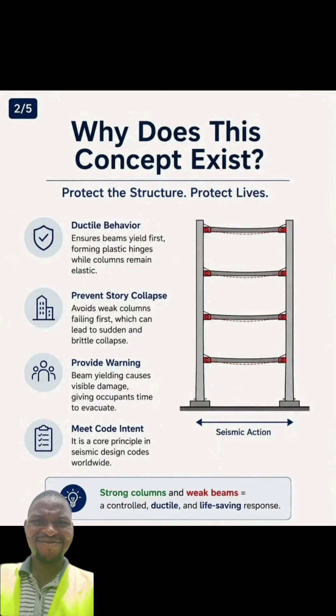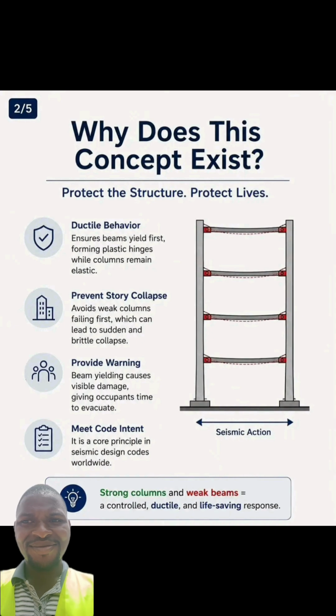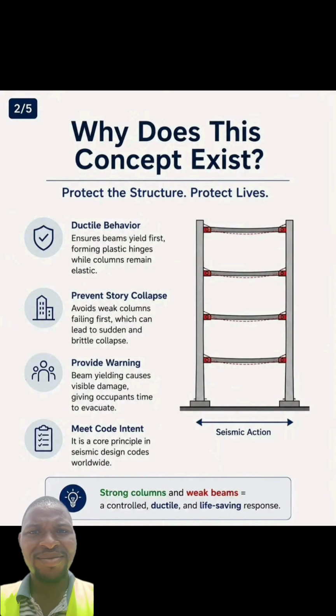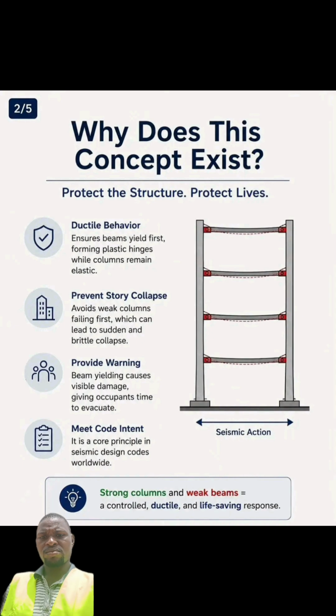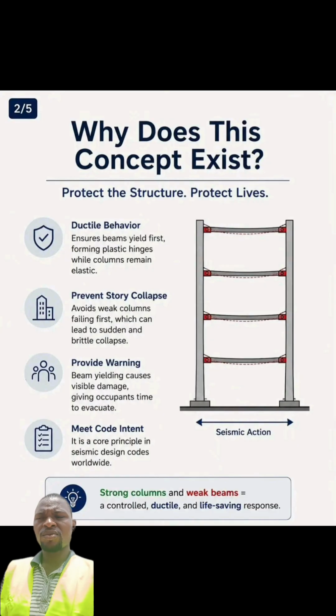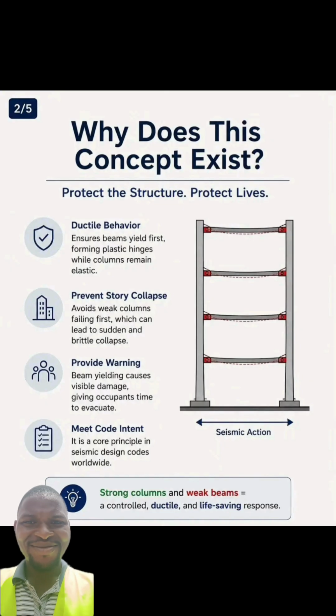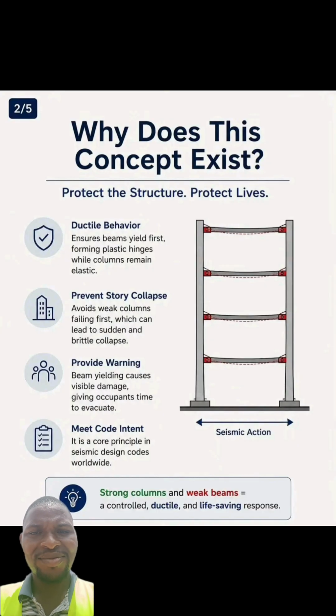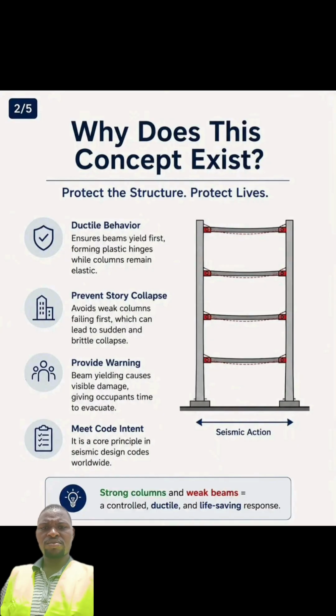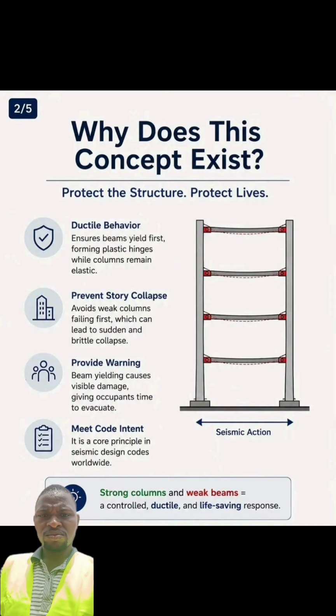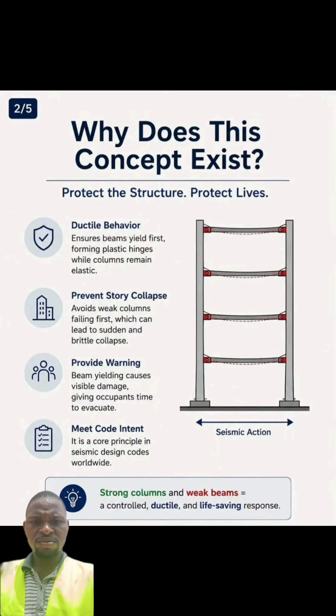Then the next point is meet code intent. Every code has its intent. It has a reason for generating such a code in construction. It is a core principle in seismic design codes worldwide. Strong columns and weak beams will always result in a controlled, ductile, and life-saving response.